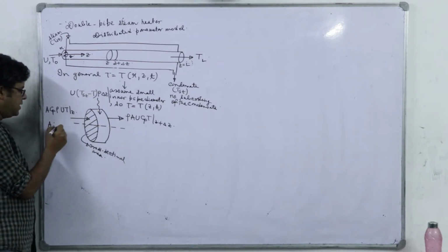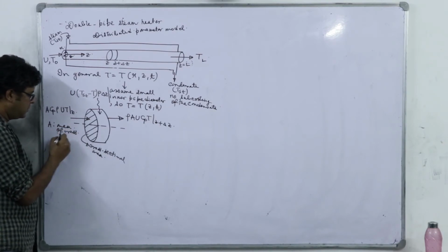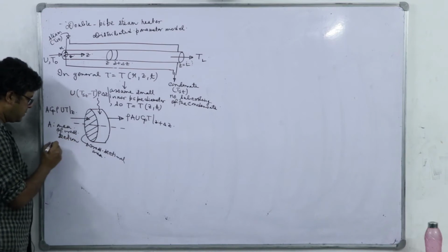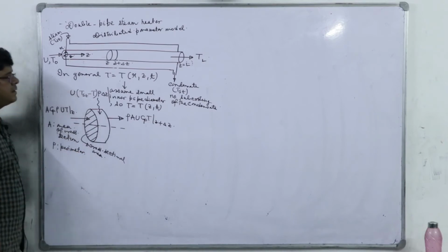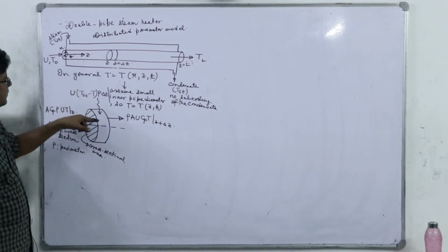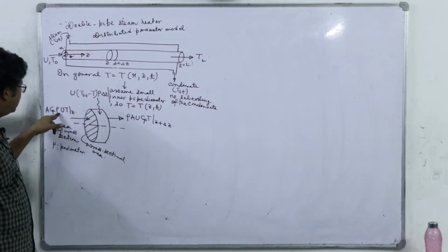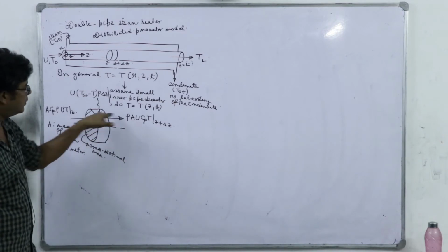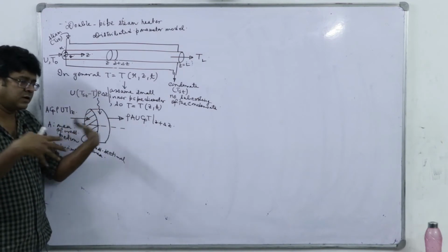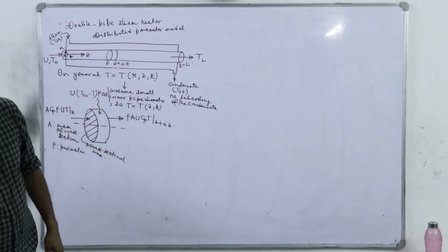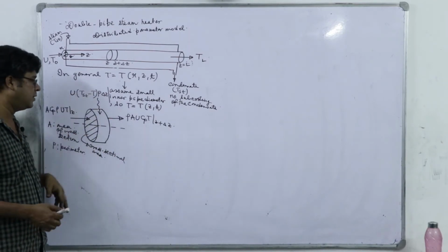A is the area of cross section, P is the perimeter. Right. So that's inflow, that's outflow, that's also thermal energy inflow. This is the flow of thermal energy because of material flow, that's also the same. Here through the curved surface we have the flow due to the energy only. This is because of the thermal gradient, there is no material flow.